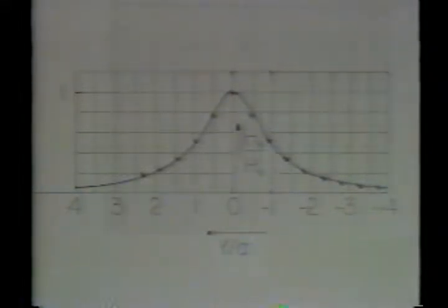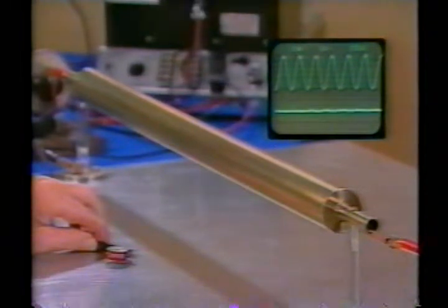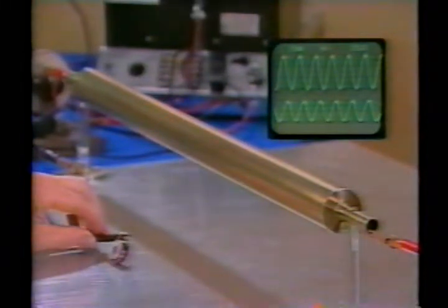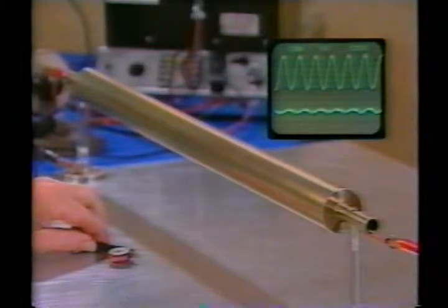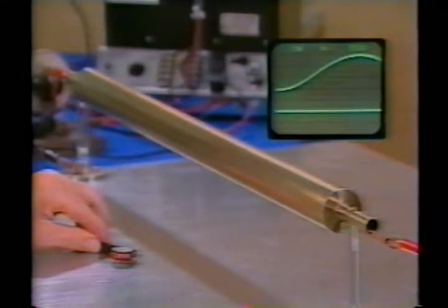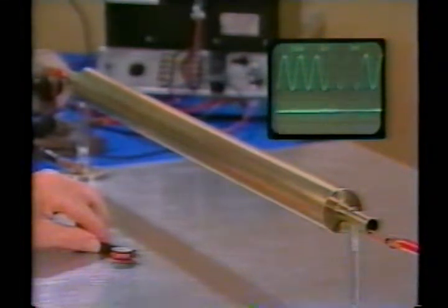If we reduce the frequency by 10 to 300 hertz, the induced voltage decreases by 10. That's just because of Faraday's law. So let's compensate by turning up the scope gain by 10. At this lower frequency, we see that the ratio of normal component to tangential component is larger than at 3 kilohertz. At 300 hertz, here's the tangential component, and here's the normal component.